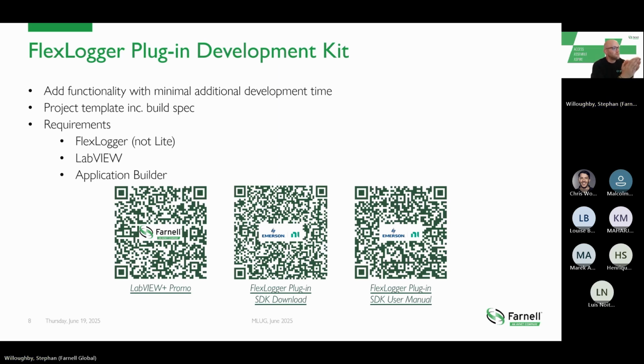So getting started, what do you need to do your own FlexLogger plugins? First thing is, why would you do it? It's if you've not got the time to develop your entire application with your data logging and all your configuration and everything else that you can do in a perfectly customized LabVIEW application, you just need to quickly do some logging. But it doesn't do, say, your pressure sensor over RS-485, you just want to wrap that up, then that's where you could use this, or to add, say, a sequencer, which I'll get to.